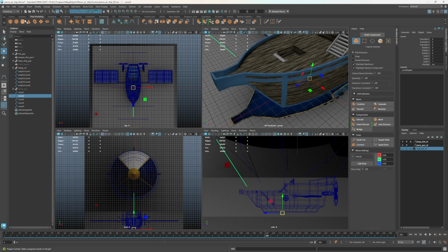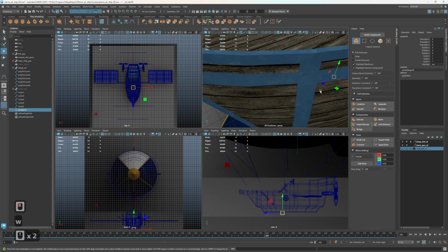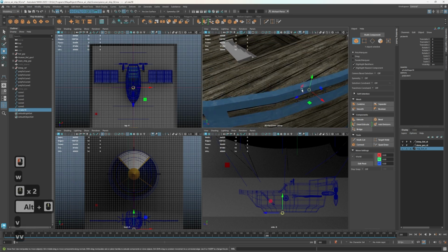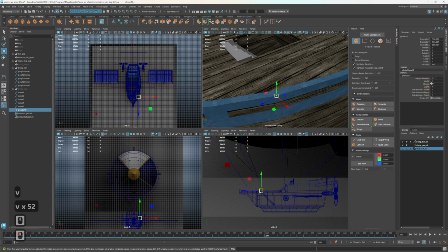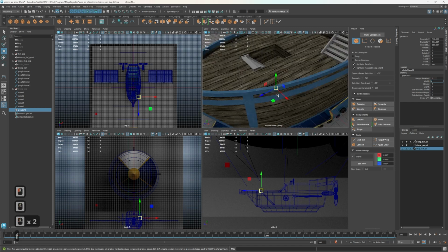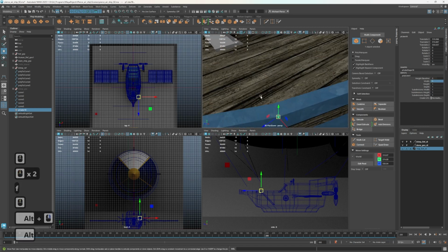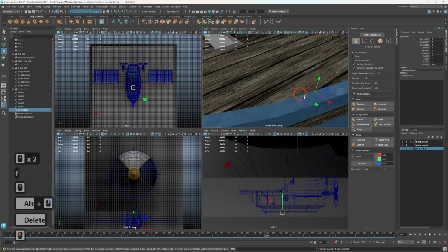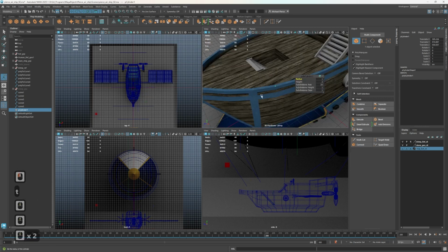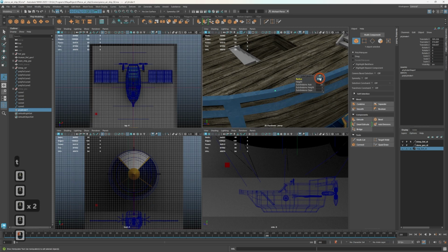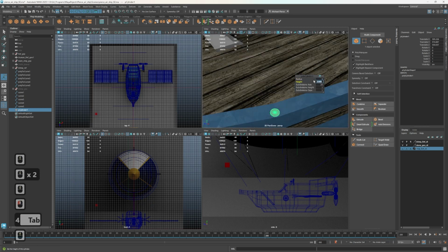In fact, I'm probably going to quickly make a little knot area. I'm going to hold V, snap it to this vertex, this corner thing, and I'm just going to do a width. No, wait, this is a cube, isn't it? I didn't mean to hit a cube. I'm going to delete that, do a cylinder. Hold V, snap it up here, make it there. Hit T so I can do some options. Radius, I'm going to make that 4 centimeters roughly.